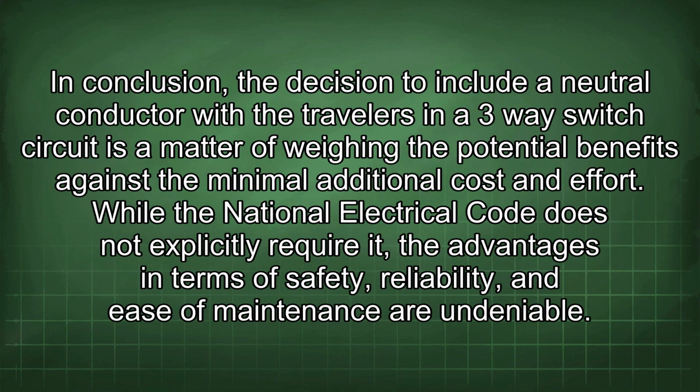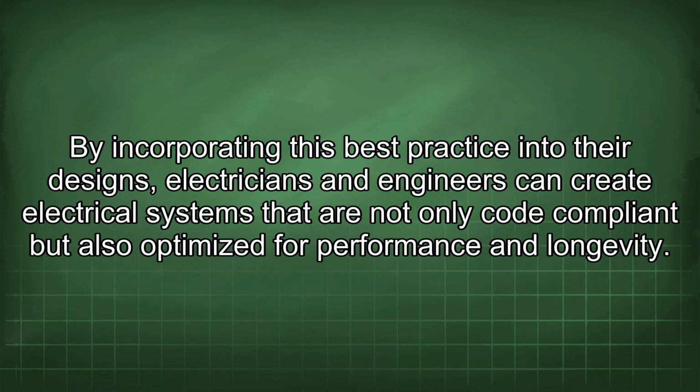In conclusion, the decision to include a neutral conductor with the travelers in a three-way switch circuit is a matter of weighing the potential benefits against the minimal additional cost and effort. While the National Electrical Code does not explicitly require it, the advantages in terms of safety, reliability, and ease of maintenance are undeniable. By incorporating this best practice into their designs, electricians and engineers can create electrical systems that are not only code compliant but also optimized for performance and longevity.